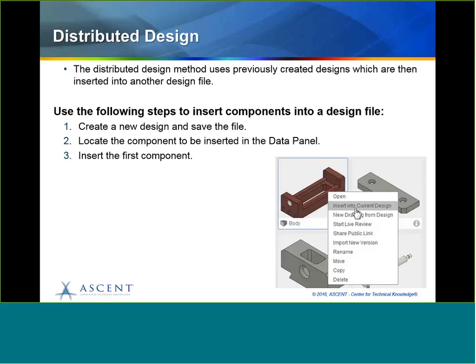In terms of the steps for bringing this together, you create a new design file, and what you need to do before you can even insert your first component is you have to save it. You're prompted for that if you start and you don't realize, because a lot of packages don't require that first save, it will prompt you that it has to be saved. And then you go in and you simply locate the component in your data panel.